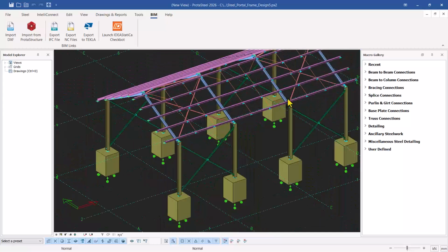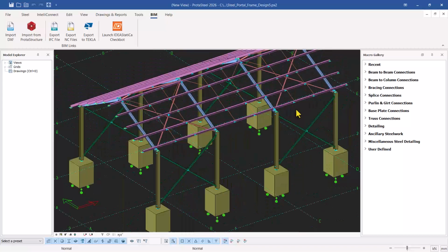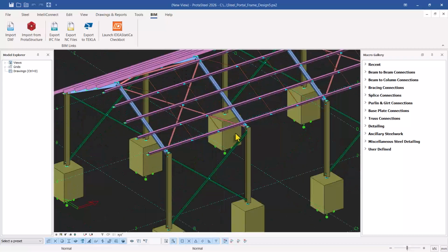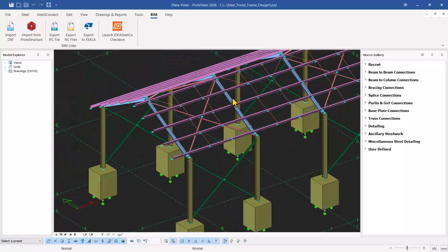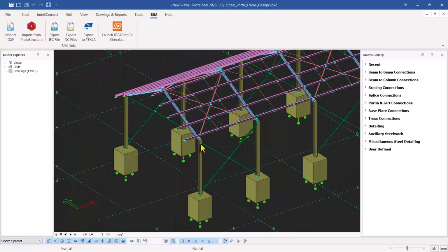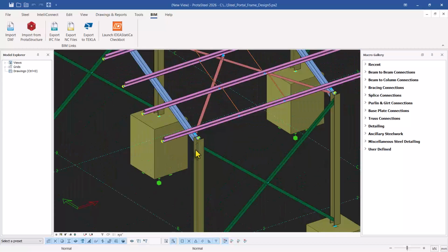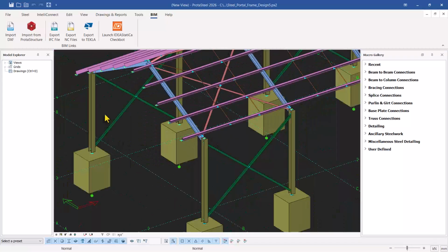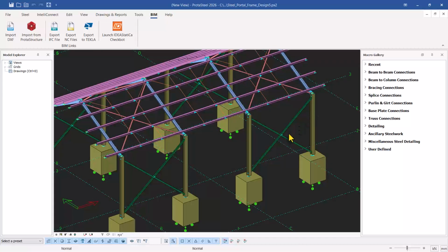All right, so every other section you can also apply. The ones that do not really need it are connections that are not moment connections, like the purlin connections and the brace connections. But for the major connections, beam to column connections, moment connections, the apex connections, and the base plate, our advice is you should use StatiCa to carry out that design successfully, so you can get it designed properly.